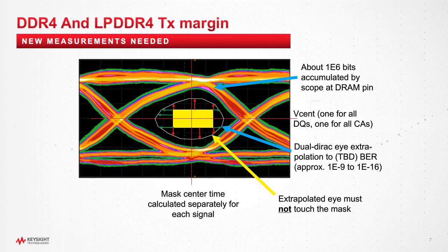And then the hotter areas, the red areas and white areas, represent places where the signal is seen a lot. And then in the middle is this black area, which ideally is where the signal's never found. And as long as that is around the outside of that yellow mask, you can expect to get a reliable data transfer.